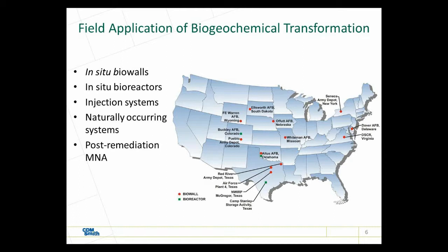I think one of the most interesting aspects of this technology is looking at post-remediation M&A. What we're finding is that if we go ahead and implement bioremediation, we end up growing a lot of bacteria, and it was previously thought, still is thought, that the bugs that are produced end up being a source of reducing power through endogenous respiration, and that can contribute to ongoing reductive dechlorination and preventing or attenuating any back diffusion that may be occurring.